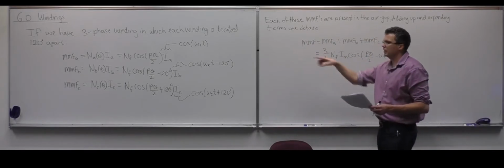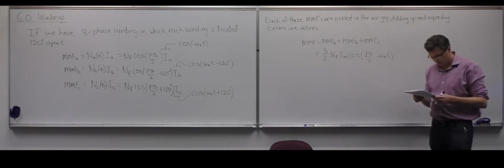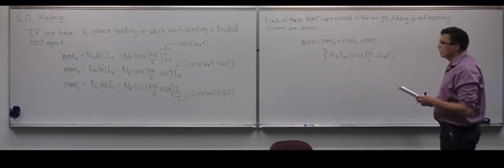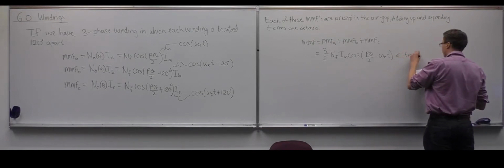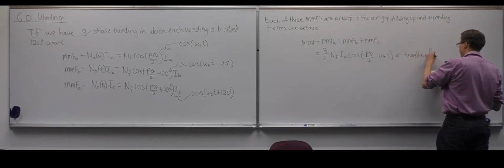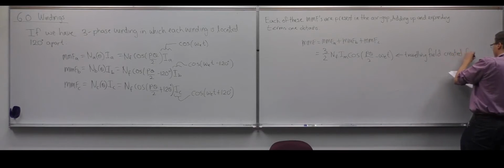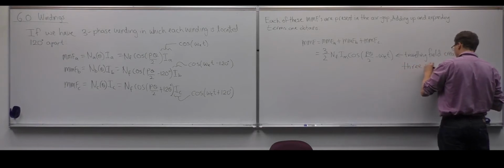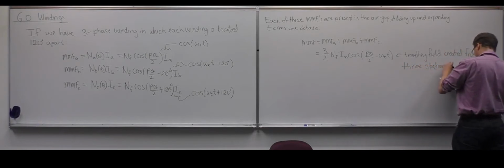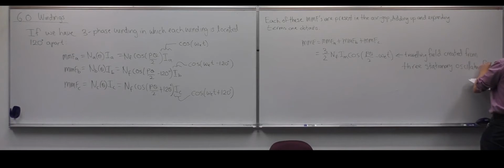But when we add the 3 up, it creates a traveling field. And so that's the key ingredient: a traveling field created from 3 stationary oscillating fields.